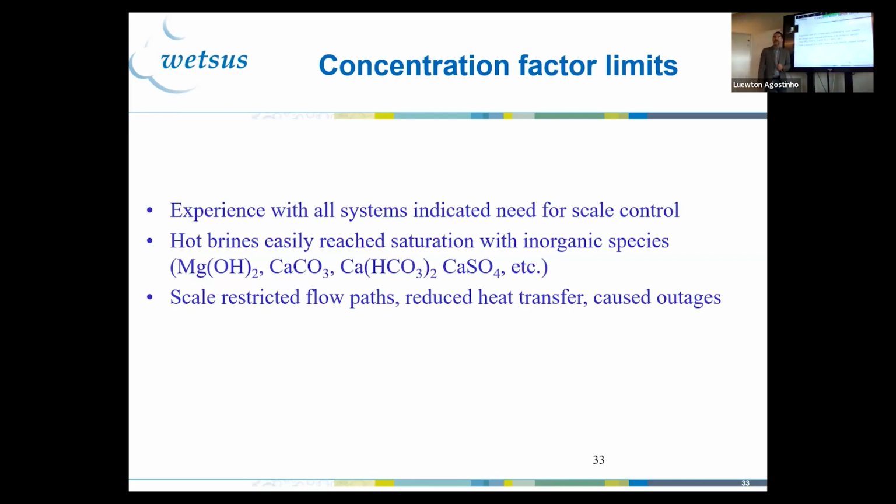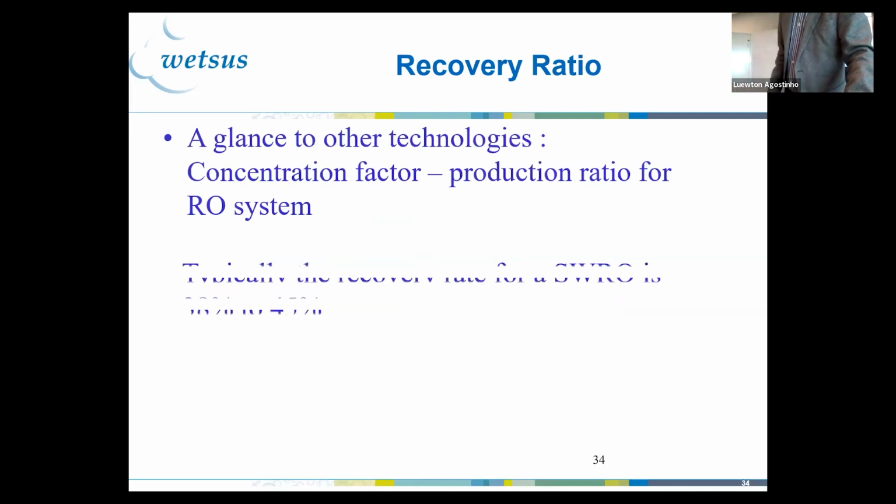Which one is the first? This guy, yeah. And then after that guy, the magnesium, right? So they are not the largest concentration of salt you have, but they are the cause of your problems. Yeah? Most of them are the cause of the problems. So scale restricts flow, reduces heat transfer and causes outages, especially when you have heat transfers.